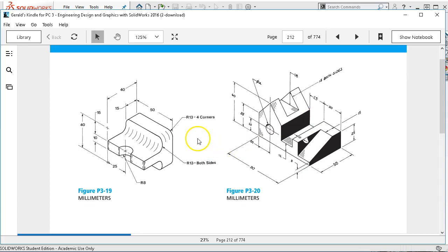Let's see, 319, not too much of a challenge here. It's just a matter of going through the geometry. What gets interesting is the selection order of the fillets can produce some slightly different results, but nothing too out of the ordinary there. One thing to keep in mind on 320 is that our dimensions, when we come down, this is not exactly in the middle of this shape. So build out your geometry and do the stack ups, but one of these legs is slightly longer, and one of these points is slightly higher than the other.